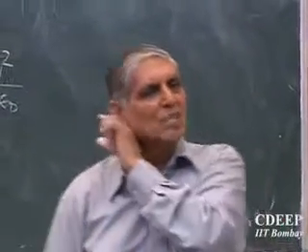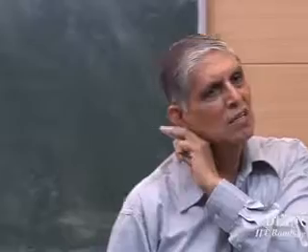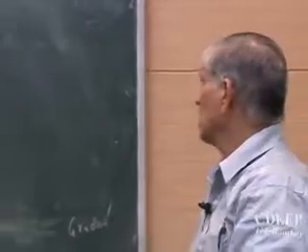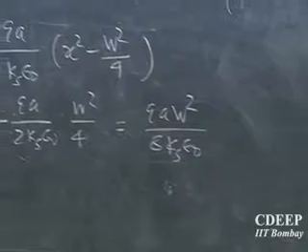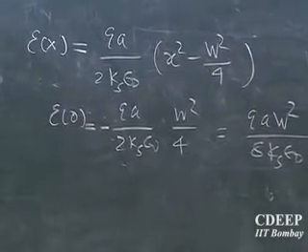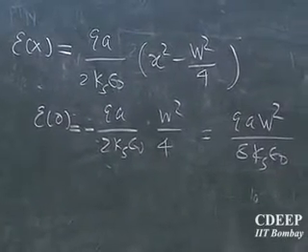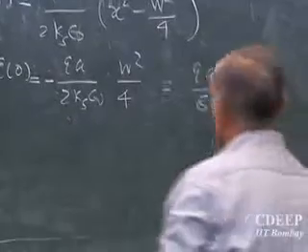So this is the maximum electric field in a linearly graded junction. Is that correct? What is the shape? Paraboloid, square law. So it's following a parabolic relationship, and the maximum field is given, what is A? The linear grade constant. So whatever slope is given to you is the grade constant.